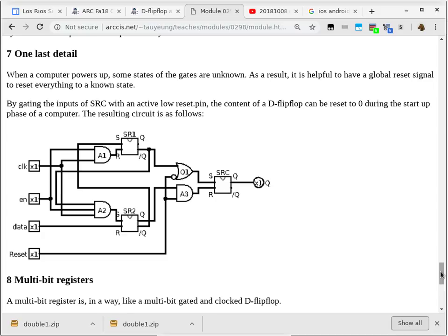So one of the jobs of the supervisor chip is to monitor that voltage and go, if it dips below what is considered a healthy voltage, hold that reset line again. So what that's going to do is, even when the voltage is relatively healthy, tell the processor, the SATA controller, and everybody else to just stop. Now, can you lose one sector because of that? Absolutely. Because if the SATA controller is in the process of writing one sector on your hard drive, you will lose that sector, but you're not going to lose any more than one sector because the processor can no longer tell the SATA controller to do something stupid after that.